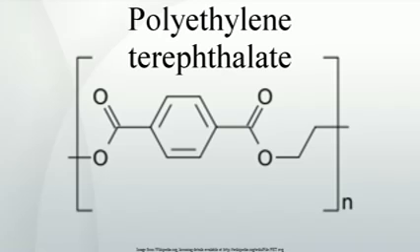Acetaldehyde. Acetaldehyde is a colorless, volatile substance with a fruity smell. Although it forms naturally in some fruit, it can cause an off-taste in bottled water. Acetaldehyde forms by degradation of PET through the mishandling of the material. High temperatures, PET decomposes above 300 °C or 570 °F. High pressures, extruder speeds, excessive shear flow that raises temperature, and long barrel residence times all contribute to the production of